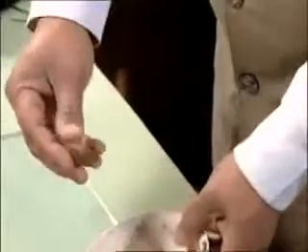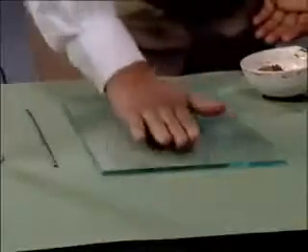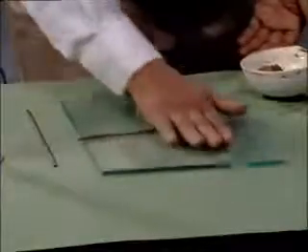Prepare a ball weighing about 8 grams out of this soil mass. Place the ball on the glass plate and roll it with the fingers so that a thread of uniform diameter is formed. The rate of rolling should be between 80 to 90 strokes per minute. Continue rolling till the thread reaches a diameter of 3 mm by taking reference of the metallic rod.